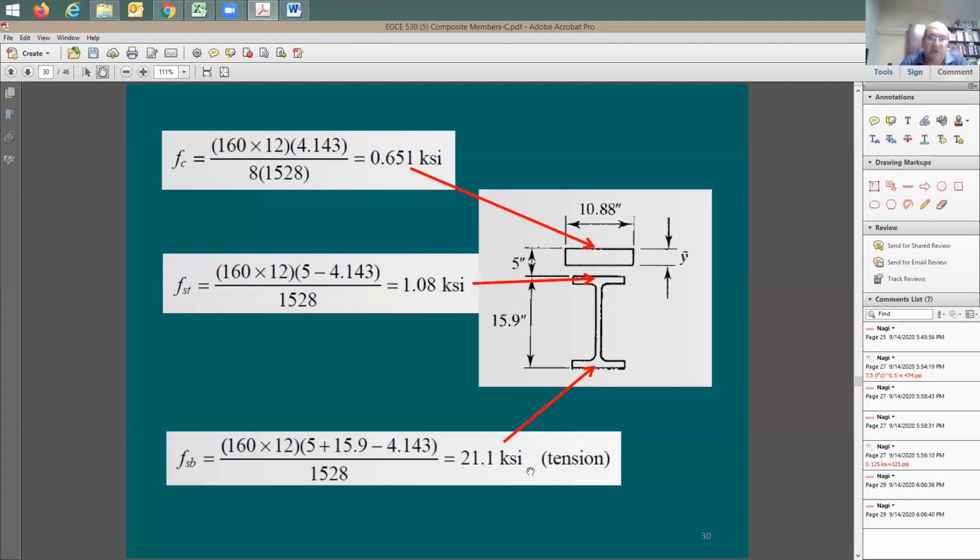I understand that usually the steel section is going to be able to take up to 50 KSI for the yield point. Now, if you're doing elastic analysis, the question to you is going to be what stress value that you're going to be okay with. When the yield point is going to be at 50 KSI, are you okay with the actual stress on the section to be 21.1 KSI or not? What stress level would you accept?